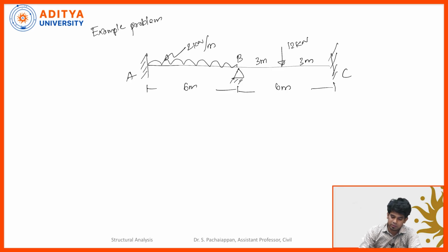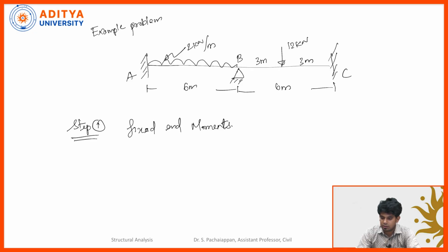In this method, as we discussed, step 1 we need to calculate the fixed end moments. For calculating the fixed end moment, we need to go span by span.